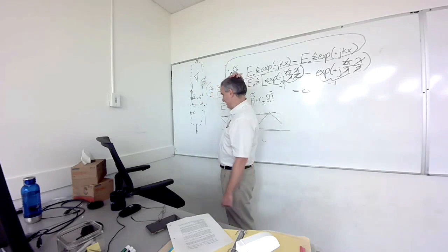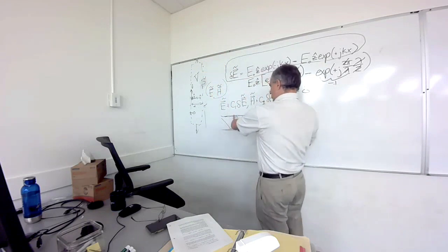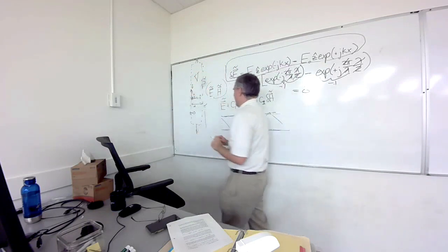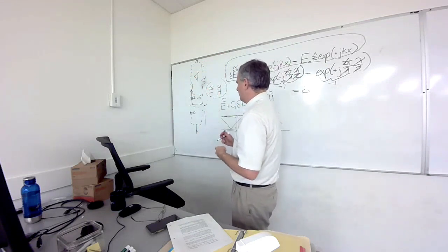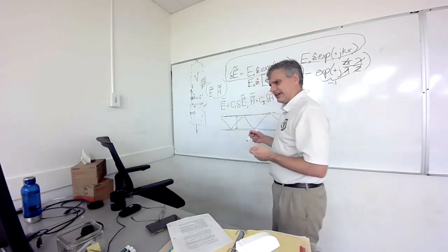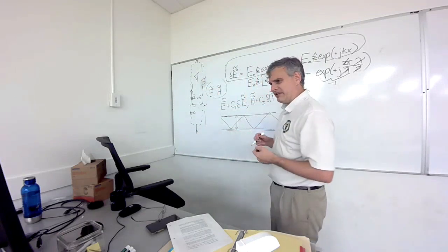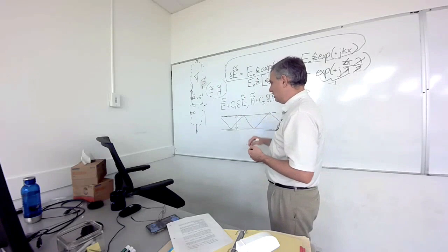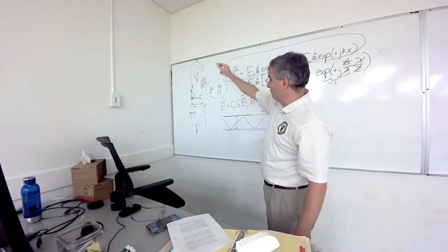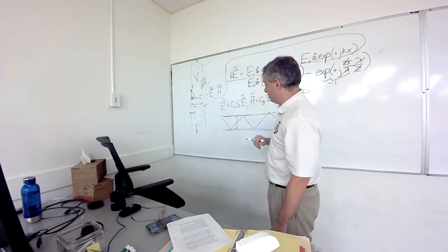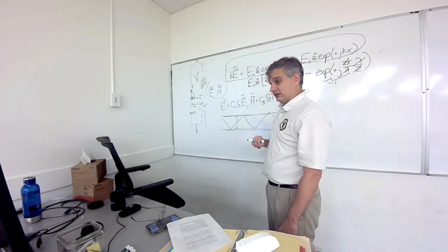That's how we get around that. So that mode that I tried to sneakily add, which kind of looks like a metallic parallel plate waveguide mode in a lossy medium, would extinguish itself long before I got to the observable region where I'm constructing my solution.